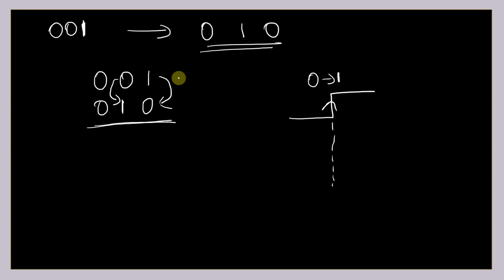Or if there is a transition happening from 1 to 0 at the exact positive edge of your high frequency clock, then it's a setup time violation, right? And let's say setup time violation has occurred. So what is going to happen? These two bits will be entering into metastable state. Now after some time they will enter into a stable state.